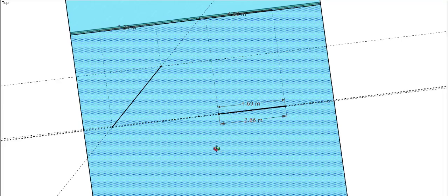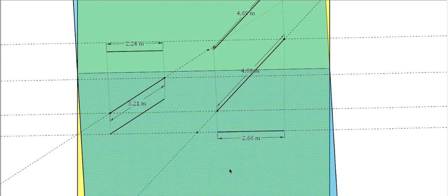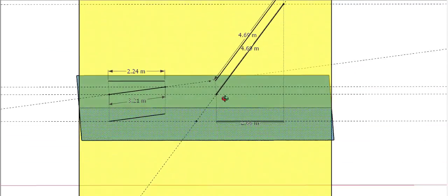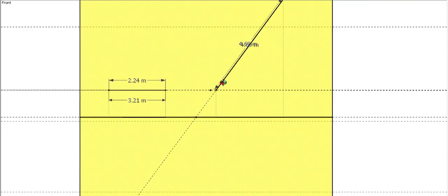Because if we are looking from the front view, we have a problem here. Why? Because it is coinciding with the XY line. As you can see, the intersection between the horizontal plane and the vertical plane is known as the XY line. If you're looking from the front, we can see that point, but when you are drawing on paper, that point is actually coinciding with the XY line.